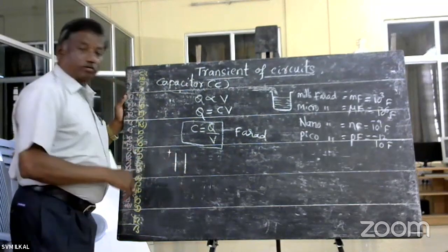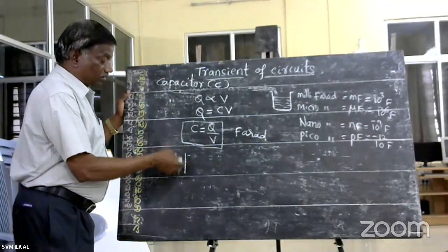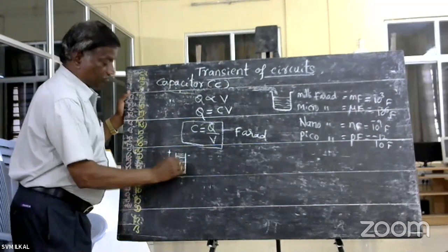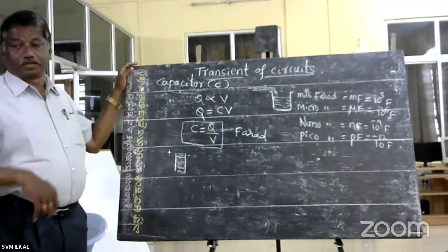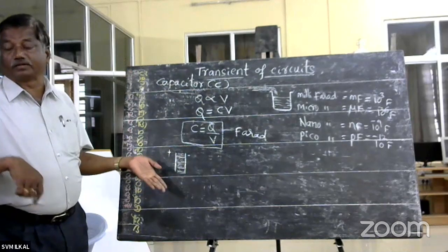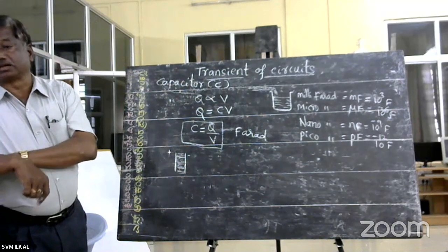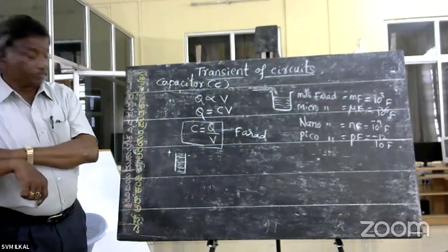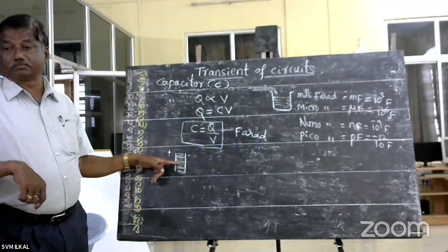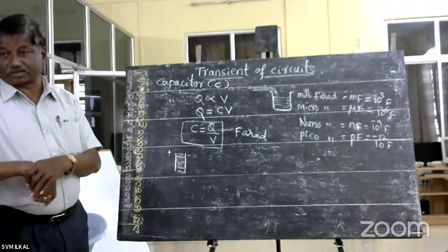Now, in a capacitor, one plate acquires a positive charge and another acquires a negative charge, separated by a small distance, and that separation between the plates is usually filled with a dielectric. Dielectric means insulating materials. Usually in the construction of a capacitor, mica, paraffin, and some dielectric materials like paper and wax paper are used. Each dielectric material has a certain dielectric constant; as the dielectric constant increases, the capacity of the capacitor increases.